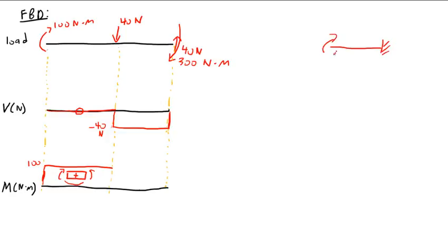If I apply a load like this, can you see that it'll want to bend in that kind of shape? So a clockwise loading applied to the end of a cantilever beam will obviously tend to put it into positive bending. Again, this type of curvature is called positive bending. Negative bending is the opposite way. It's a frowny face.